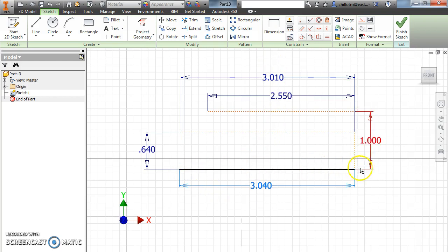We have our one line here, and we're going to need to arc it from here to here, here to here, and then one more arc down at the bottom. Alright, so I'm going to choose my arc command. I'm going to start down here and go to here. Okay, and what number do I need? Well, if we take a look at the sheet, that first arc has a radius of 6. So I'm going to type that in. 6. There's our first one.